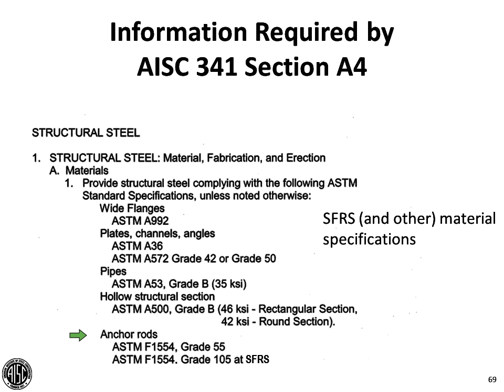One point I want to make with respect to the anchor rods is that generally speaking, we try to use the lowest grade anchor rods that we can rather than specifying a single grade, unless that lowest grade works for everything. But what we find is that for gravity systems, either the grade 36 or grade 55 usually work. But for the seismic, we often find ourselves having to rely on the grade 105.